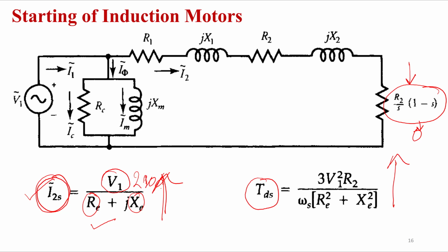Yes, we put an auto transformer. So there are various methods devised in the literature, and we'll find in the books: auto transformer, delta starters, and many methods which actually minimize the input voltage during starting condition, right? We are not discussing these in detail. One method you are doing in your laboratory is simply starting from 0 voltage and gradually enhancing it to the rated voltage, right? So that is one method.